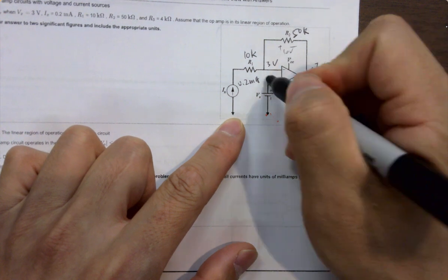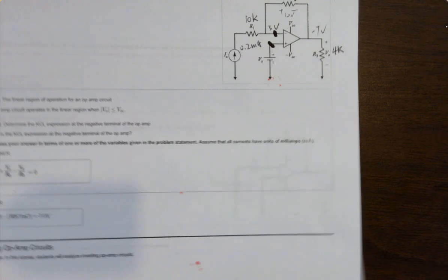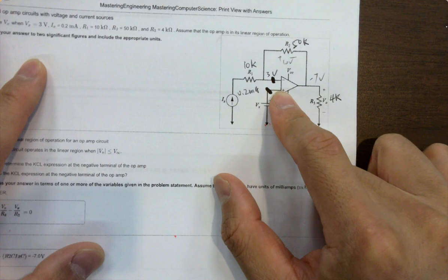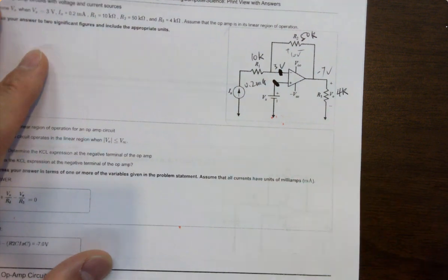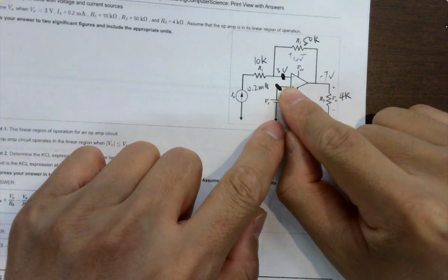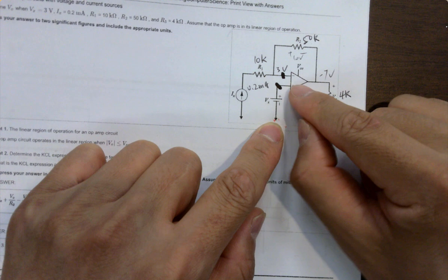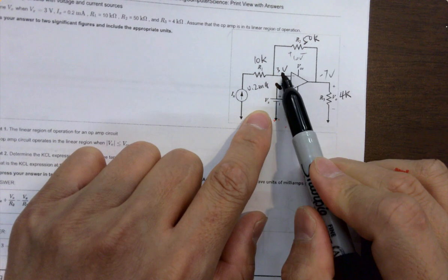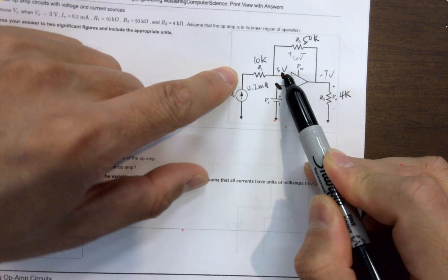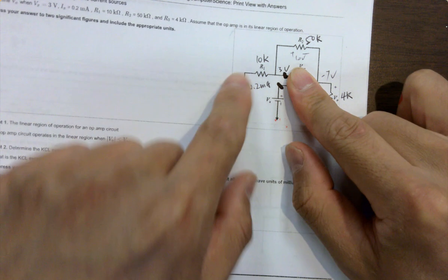Now it's not grounded. So it's Vx. What's the voltage here? You cannot just memorize it as virtually shorted to ground. It's virtually shorted to the other terminal, not ground. Keep that in mind. There are 2 concepts confusing people: virtually grounded and virtually shorted. It's actually virtually shorted to this point. If this point is grounded, then this is virtually shorted to ground. If this is not grounded, it's not virtually shorted to ground. So Vx over here is going to be Vx here as well. They're equal, virtually. So if you know this is Vx, you know the current here. It's just a very simple KCL problem. Ignore this guy. The current flows that way.